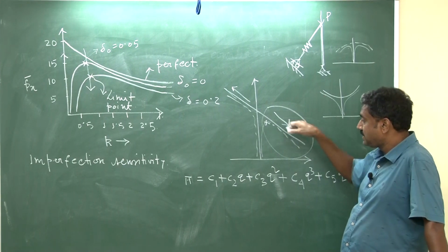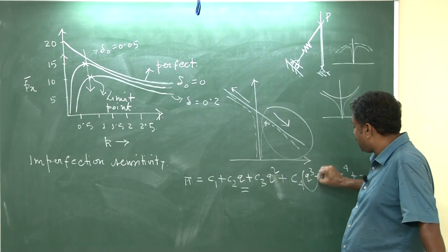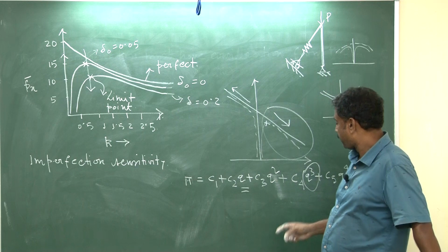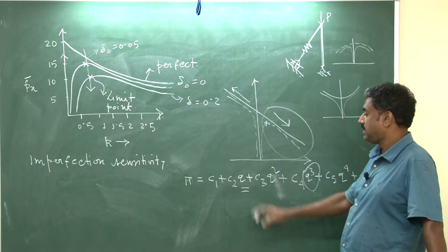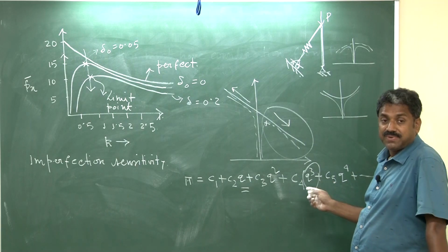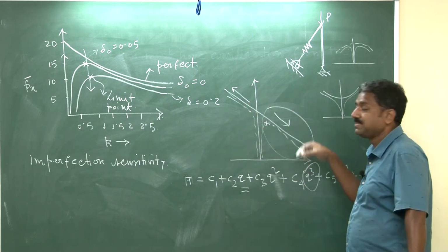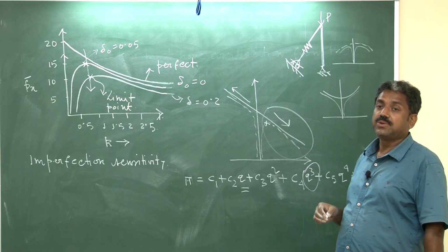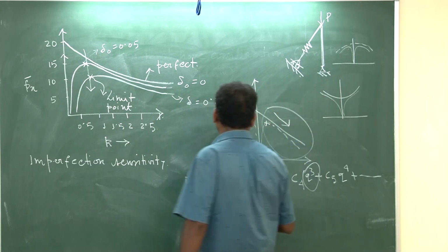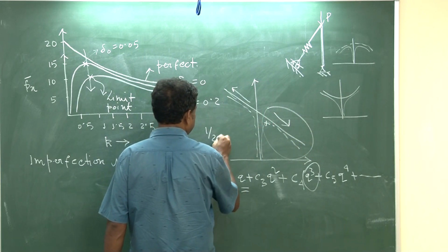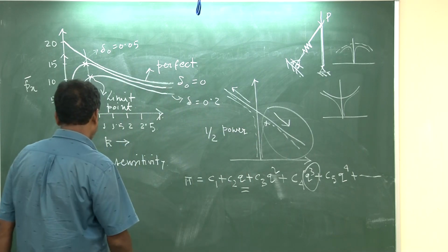But when there is an asymmetric path, it will have a cubic term; this cubic term becomes important. Of course, the function has to be quadratic, so the lower terms do not really matter. So, the cubic term will be present. Shell buckling involves this cubic term, that is why there is asymmetry in bifurcation, and because of this cubic term it shows imperfection sensitivity. And what kind of imperfection sensitivity does this show? Half power imperfection sensitivity. How do you explain that?